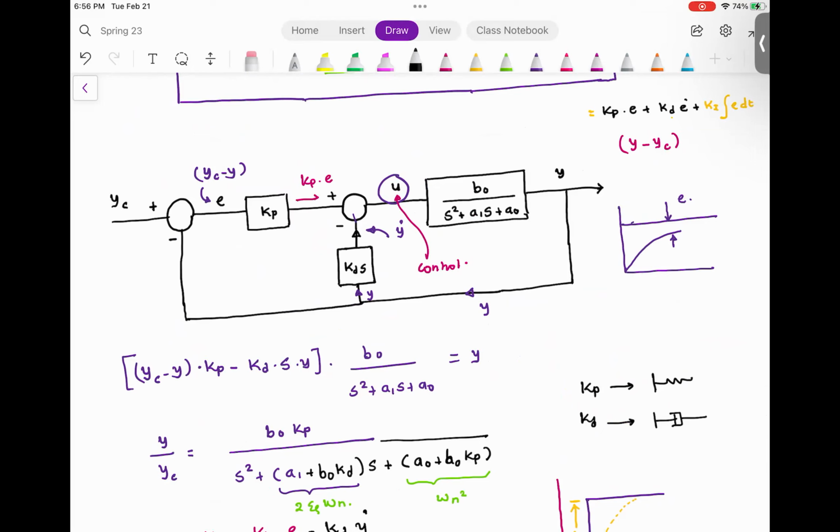The next question is, how would you implement this on a microcontroller? Microcontrollers do not work in a continuous domain, so time is discrete. So you have this continuous transfer function, and you will have to use something called the Z transform to convert that into a discrete transfer function. The MATLAB toolbox can take a continuous transfer function, which is defined over here. This is not a discrete form. You have to use the Z transform to convert this transfer function into a discrete form.